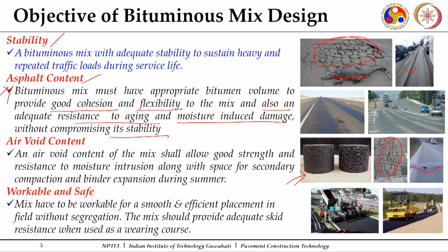So, what you need to see? You need to see the asphalt content which is appropriate for a mix. You need to see that it gets good strength out of it. Air void content: when you prepare these bituminous mixes in lab and field, there will be some air entrapped in them. They will not be completely voidless mixes. A general conception is that the more dense a mix is, the stronger it will be. Yes, with the increase in density, the strength and load carrying capacity can increase, but there are certain challenges also which need to be understood.